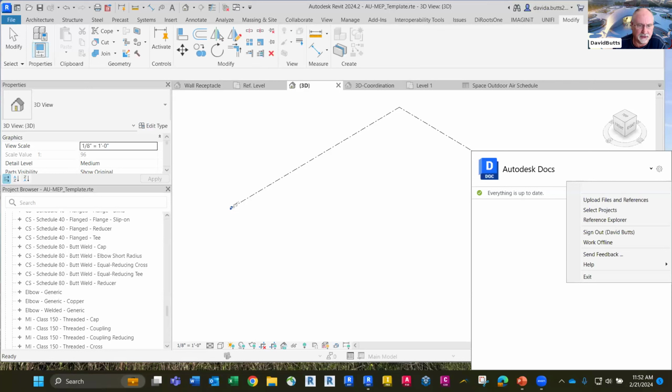That was the big thing for me. I wanted to be able to print a whole set and have a predefined value set. I use the Publish command and use sheet lists all the time. I found that to be more stable. It's a simple DSD file that does work in ACC. It is supported. So it's really simple to keep that one file in there and just have that sheet list that you can actually copy and share.